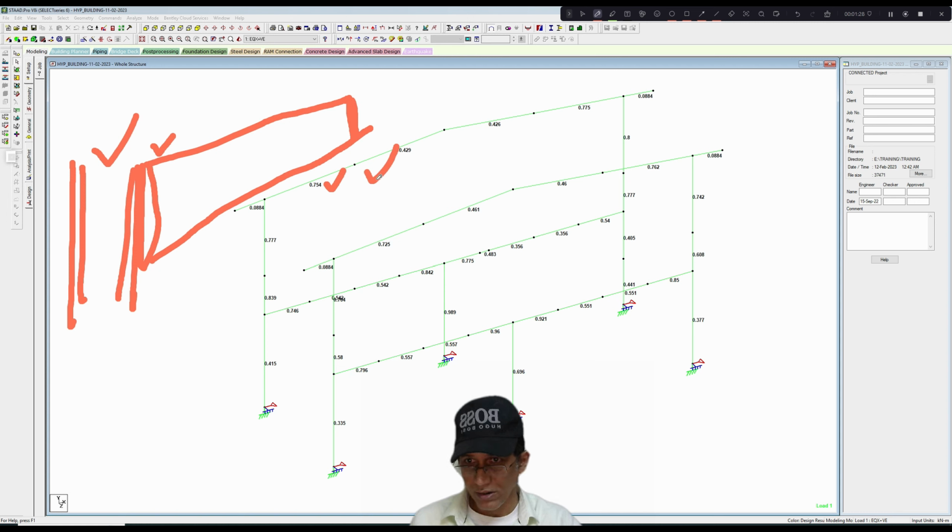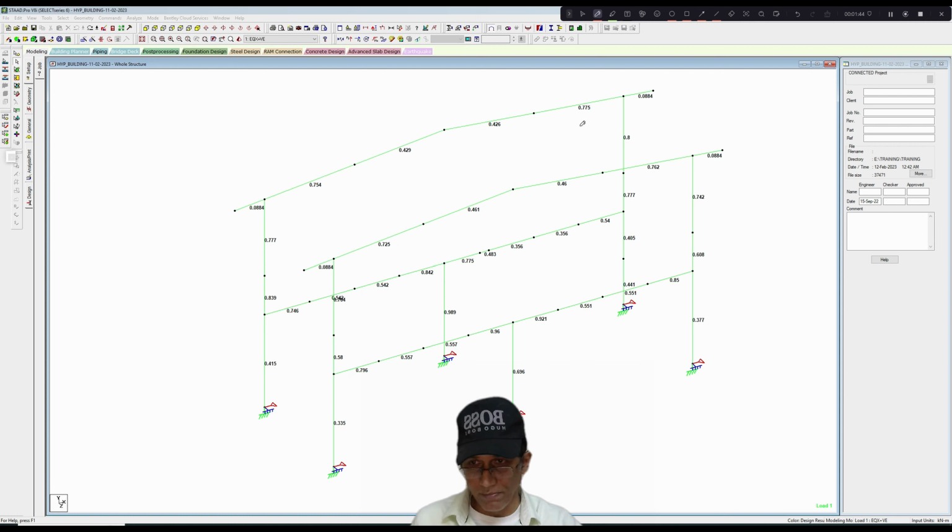So that is why we are not going to reduce the section depth here, uniform section depth, and we will define the tapered section with this section itself. We have column depth as 366 here, 376, 370. For all practical purposes we shall treat both of them as total 370 mm. So this is 370 mm.